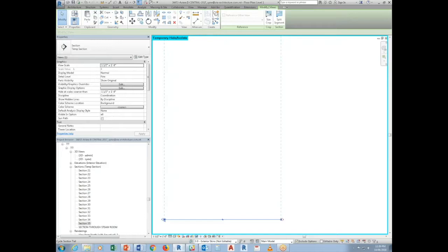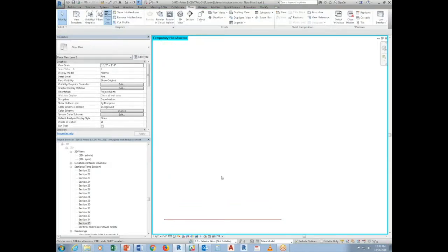Okay, any questions so far with any quirks? I have a question. Probably you mentioned at the beginning, the working views and sheet views. Right. Okay. So I know in certain projects they have working views and sheet views, correct? The problem with Revit is that the more views you create, it adds more file size to the project, and sometimes it balloons your file by about 10 to 20%.